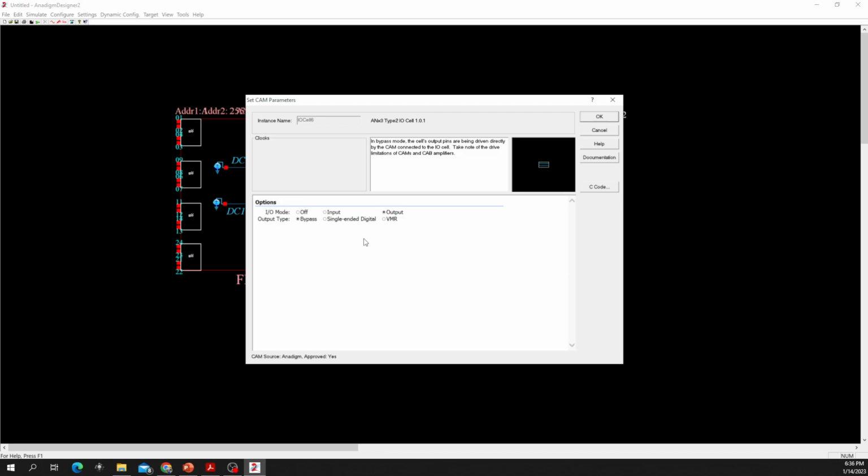So you might be wondering what single-ended or VMR are. VMR itself is basically a constant voltage representing 1.5 volts. So in FPAA, the Anadigm company generally makes your 2 differential input or output signals center about 1.5 volts instead of 0 volts. That's just their internal design. So we don't have any solution to change it. Let's just agree with bypass for right now.